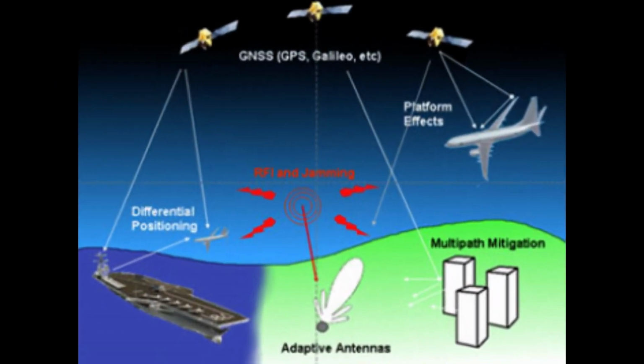Unless authorized by ATC to operate an aircraft within controlled airspace under IFR, pilots must either fly along the centerline when on a federal airway or, on routes other than federal airways, along the direct course between navaids or fixes defining the route. The regulation allows maneuvering to pass well clear of other air traffic or, if in visual meteorological conditions, VMC, to clear the flight path both before and during climb or descent.